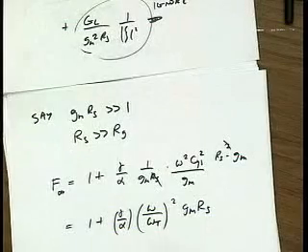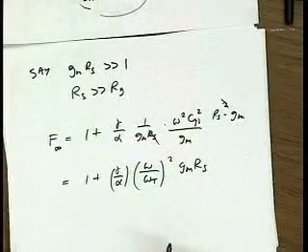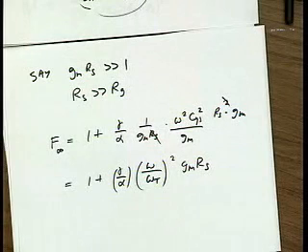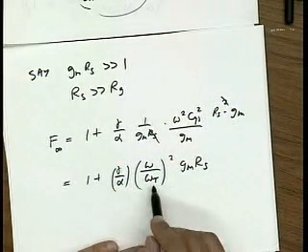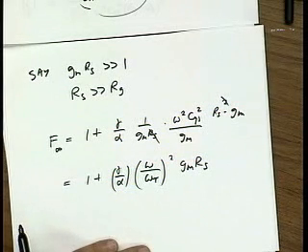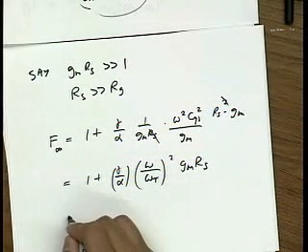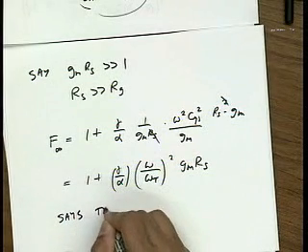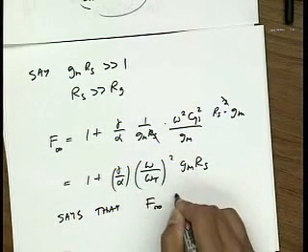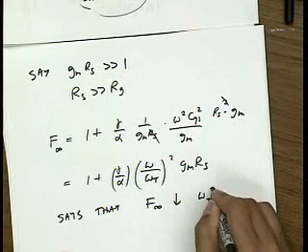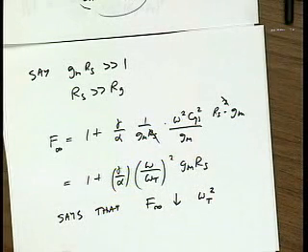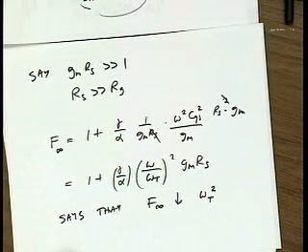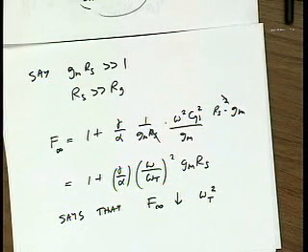Okay. So this shows me that in the limit at high frequencies, using the simple model that we just used, the noise is strongly dependent on the omega t of the transistor. So this says that noise goes down like omega t squared, which is in fact very nice because as we scale technology, a lot of bad things happen to transistors, but one consistently good thing is that omega t gets better.